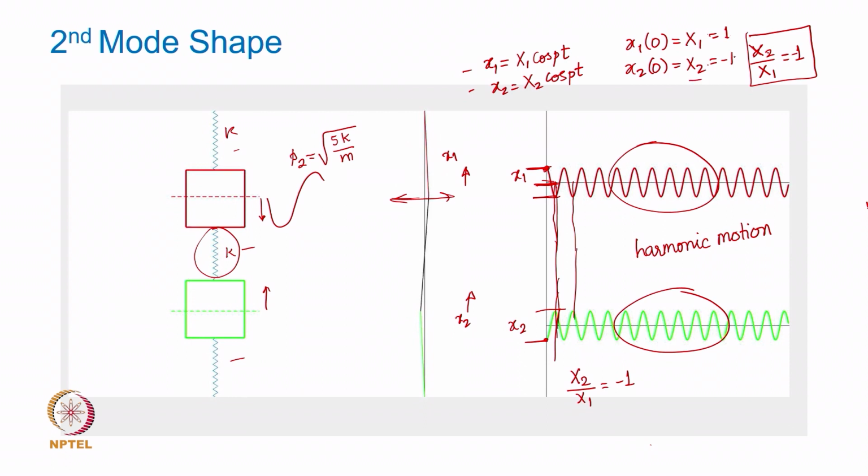should be given in a way that it satisfies the mode shape, and only when I give this kind of initial displacement, then the subsequent vibratory response happens in both masses at its natural frequency. Okay, both the masses move harmonically, both the masses move with the same frequency, either P1 or P2, depending upon how I initially perturbed them.